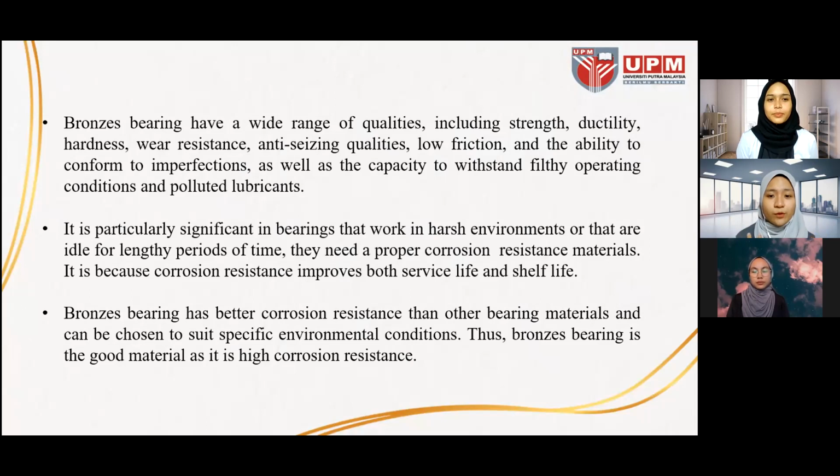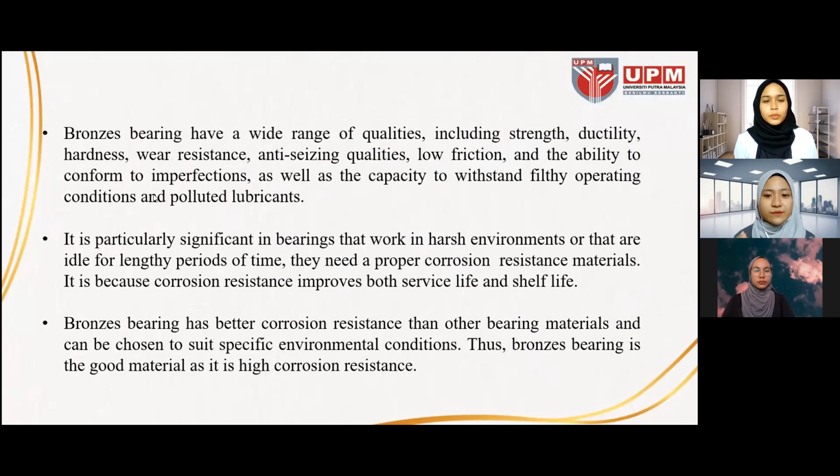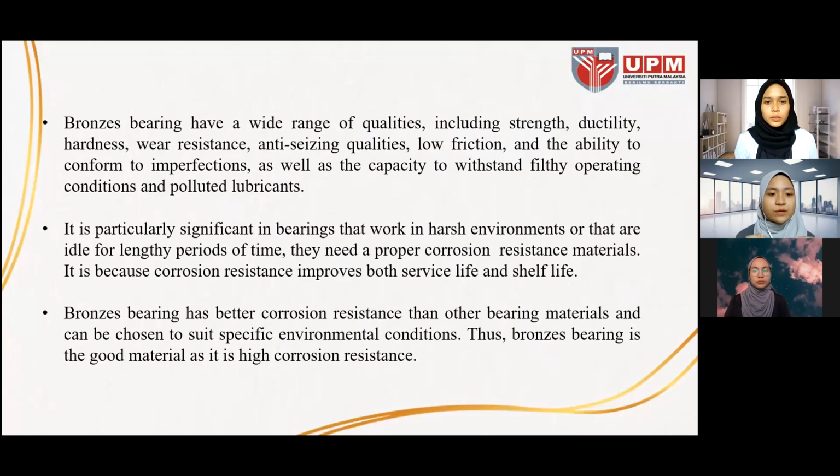So they need proper corrosion resistant materials, because corrosion resistance improves both service life and shelf life. Bronze bearing has better corrosion resistance than other bearing materials and can be chosen to suit specific environmental conditions. So bronze bearing is a good material as it has high corrosion resistance. So next.